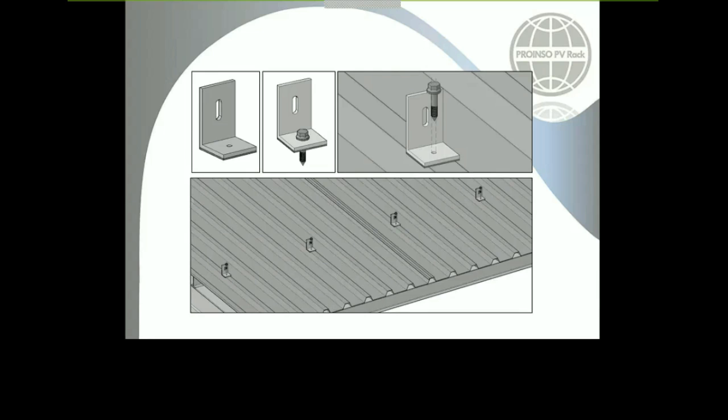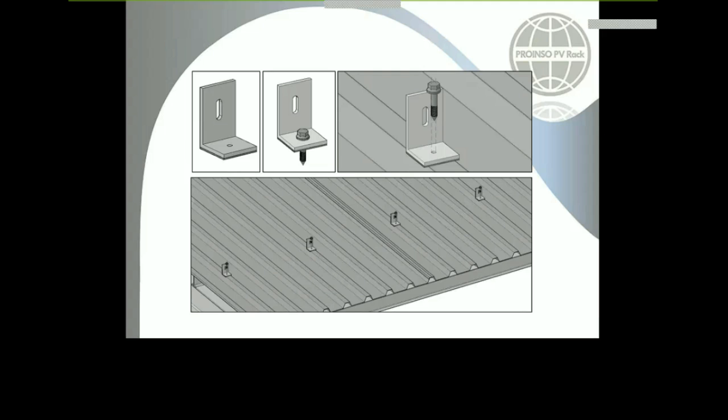Anyway, you could avoid this kind of effect by putting some EPDM rubbers, or there are different solutions as well, some washers that avoid the connection between one and another. It usually happens with hot dip galvanized steel, I think. But in the case of aluminium, I've never seen this before.